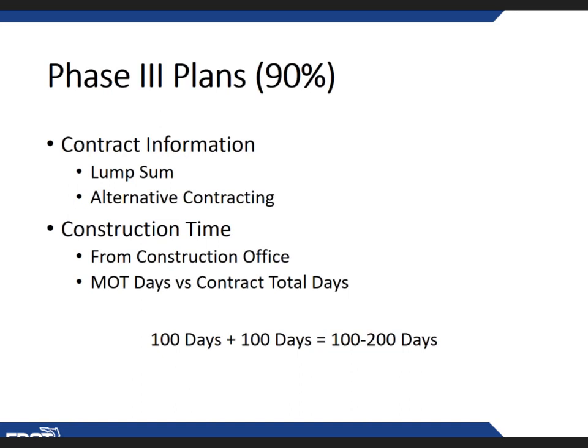And this is just a heads up, because I've seen a lot of projects that were combined or strung together at the last minute, and when a project is strung together with another one, you do have to stop, go back, and get that scheduling engineer to look at both projects together to determine that total. Because if the second project can be completed simultaneously with the first project, there's no reason to add any more days. You just stay with 100 days.